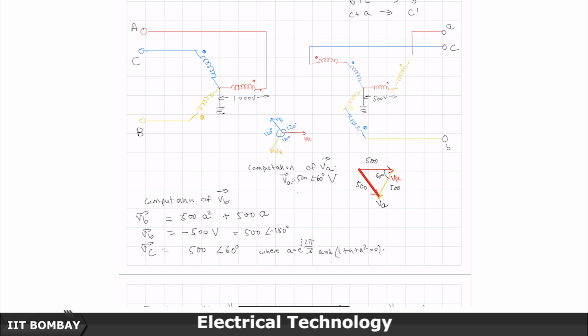So, you can see that A phase is 500 minus 60, then subtract 120 degrees from it, and B phase is 500 minus 180. Automatically you can conclude that C phase will be leading, and you can verify it, by 120 degrees. So, minus 60 degrees plus 120 degrees will give you plus 60 degrees, and the equilateral triangle will still give you 500 volts. So, the VC will turn out to be 500 angle 60 degrees. So, this is the voltage.